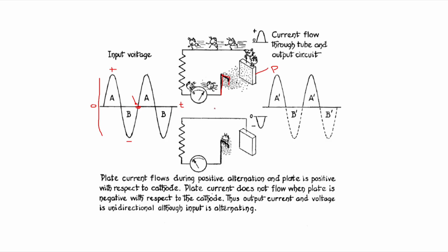So we are going to see what happens when we put AC in. It's the same thing that happens when we put DC in, basically. So let's start out during our positive half cycle right here. And we're putting this voltage on the plate, by the way. It's depicted right here, 0 to positive. That means the plate is going to start swinging from 0 to positive, and we know what happens when the plate goes positive. It attracts electrons and a current flows based on the internal resistance.